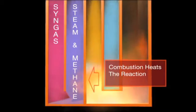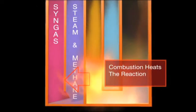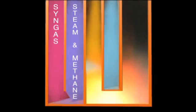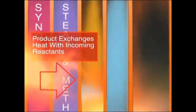Heat from combustion is used to drive the equilibrium-limited steam methane reforming reaction, which is most effective at temperatures above 850 degrees Celsius. In the process channels, steam and methane are converted into synthesis gas or syngas, which consists primarily of hydrogen and carbon monoxide.